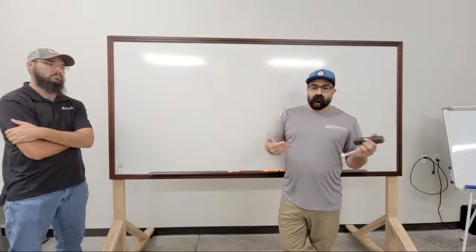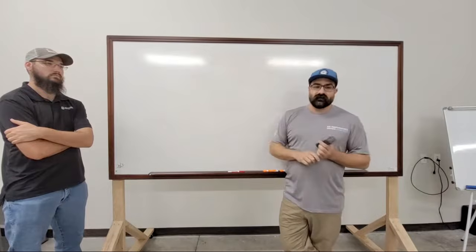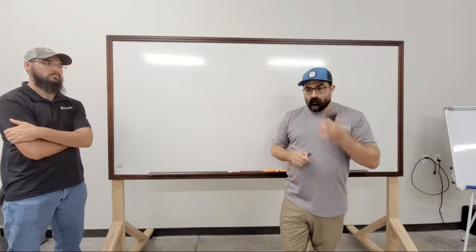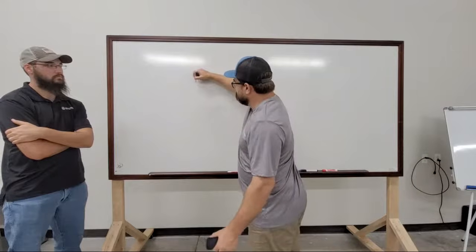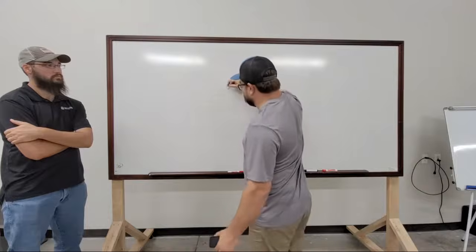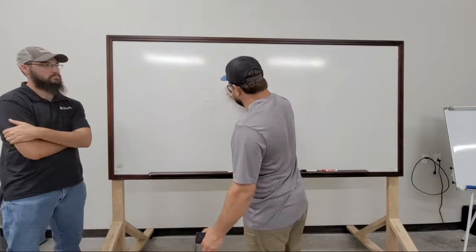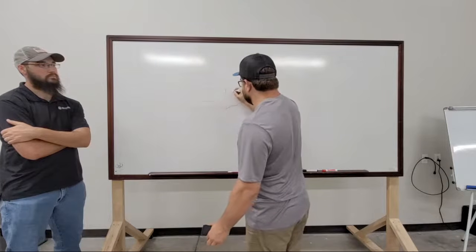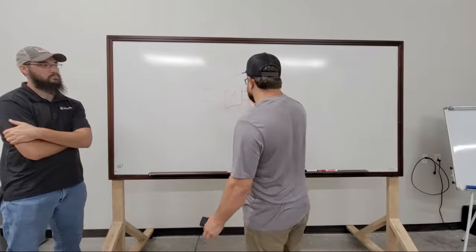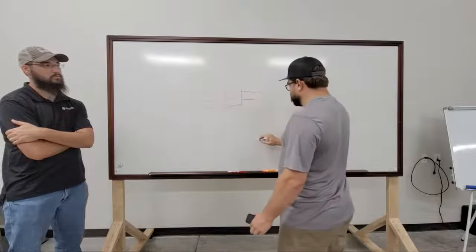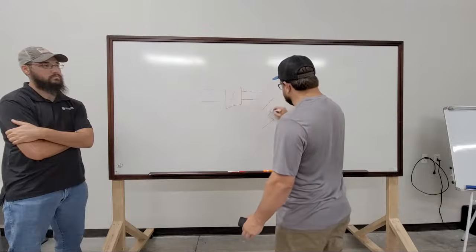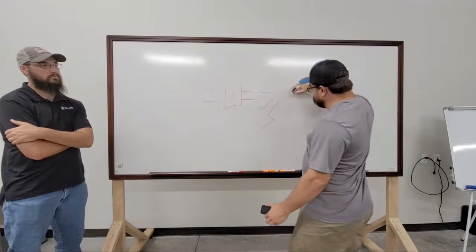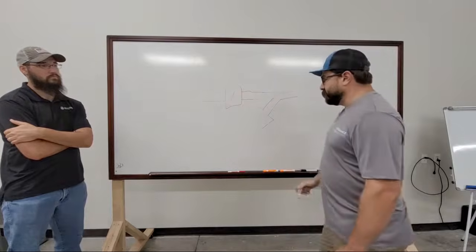If you don't know to look for that, you won't find it because it's 10 feet down the duct line. We get that sometimes where you'll have a piece of ductwork, a VAV box with a little damper in the middle, and then somebody decided they wanted to be cool and put a fan in a little bit down the line. And it's now a fan power box.